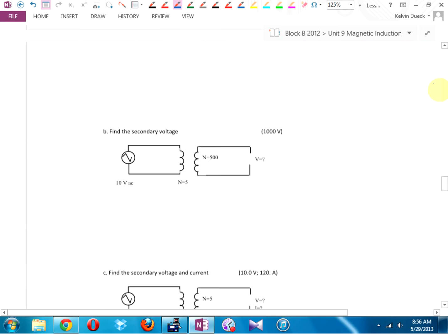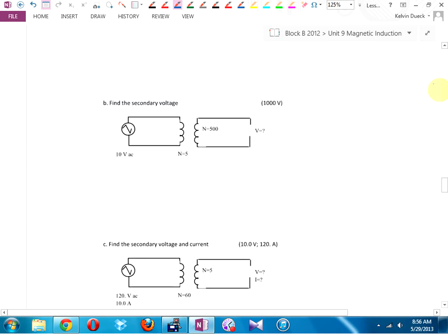Let's try another one. So for voltage and the number of coils. By the way, now you're starting to see why maybe that EMF symbol isn't such a bad idea after all, or maybe we need like 50 letters in our English alphabet. No, we'll use Greek. Go ahead. So we can put primary or secondary on the top as long as the current switches. If you put primary on top for coils, then for current, primary is on the bottom. Yep, but you can switch it around, because when you flip both sides of a fraction, it's the same. In fact, I have a habit of doing primary on top because that's just what I look for first, and that's how I write it. I grabbed Graydon's formula sheet and I think they put secondary on top in the formula sheet, and that's fine too.